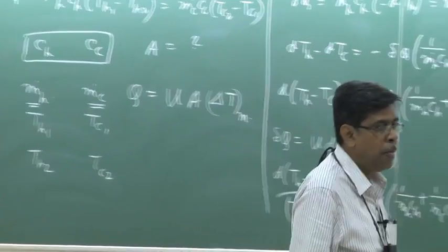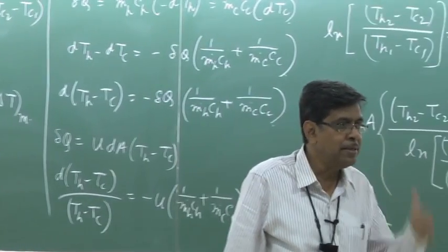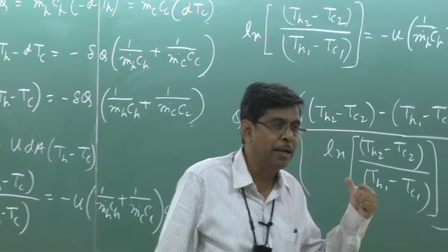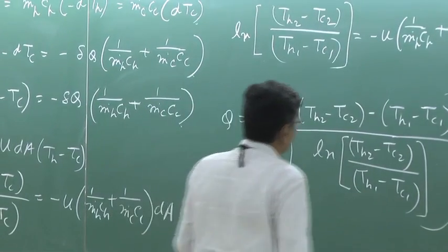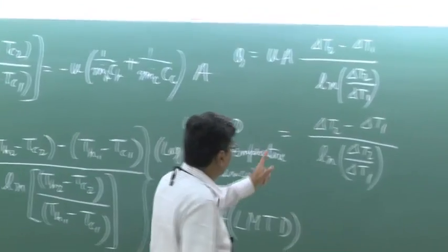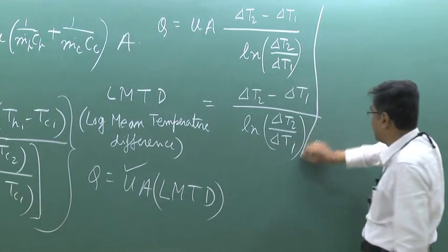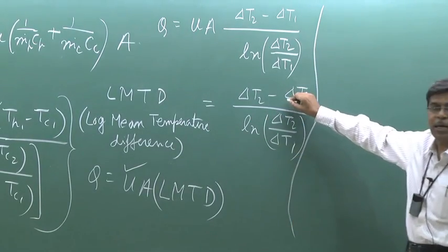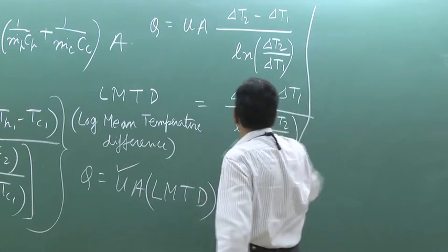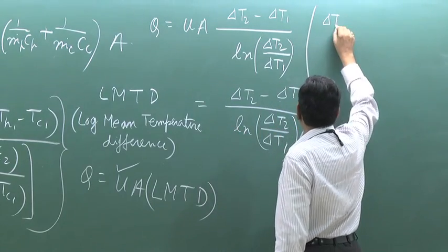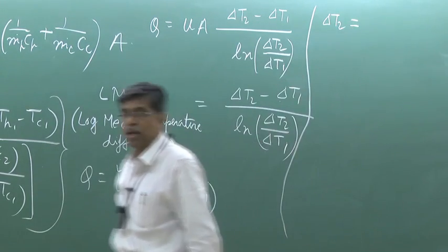Now there is a clue, very important. If it is a counterflow heat exchanger, how will you derive it? First of all, a counterflow heat exchanger uses the same formula, but what is delta T2? For a counterflow heat exchanger, the generic formula is this one. Delta T2 in a counterflow heat exchanger can be taken on either side.